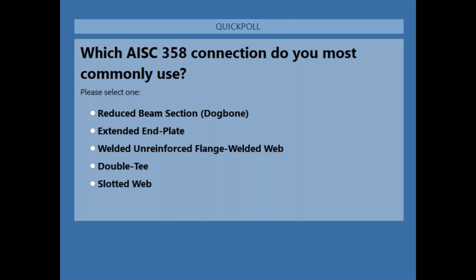And I'm pulling up the... yep. So here's a good question as you are answering that poll, and it has to do with the clips on these stiffeners. I believe, and I'm going off of memory here, Colin, you could correct me if I'm wrong, but I believe for the seismic requirements on these stiffeners, we have to clear that K distance on the column by at least a half inch?